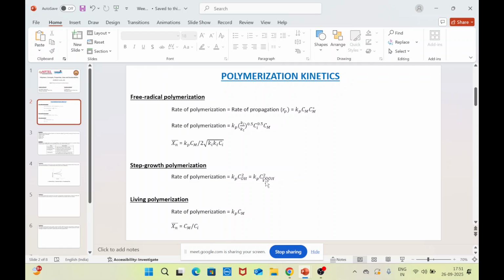Okay, so we will have a question related to this. Let us discuss more about these three terms when we are discussing that particular question. Apart from that, we also have to discuss something called the melt flow index, which is an industrial parameter. It measures the amount of polymer melt that flows out of a die under a standard mass in a given time. So how much polymer actually flows out of a particular die under a standard mass and a given time condition is called the melt flow index.